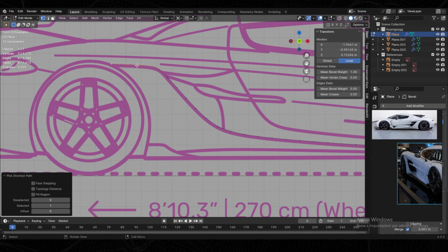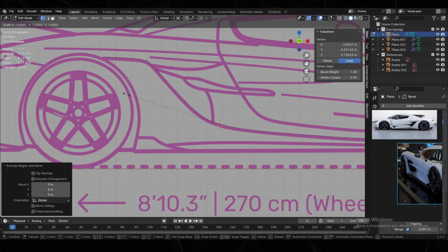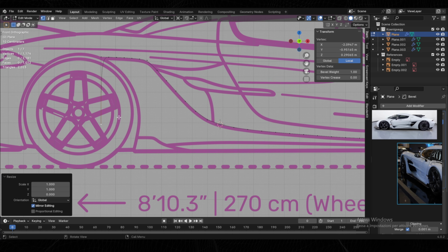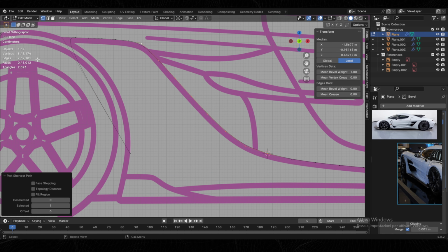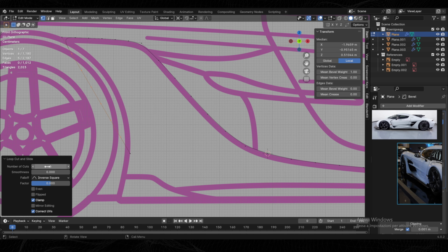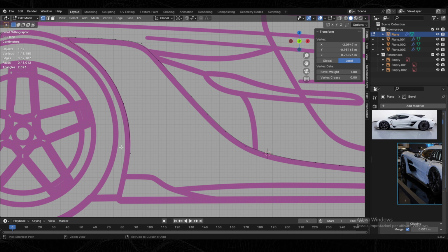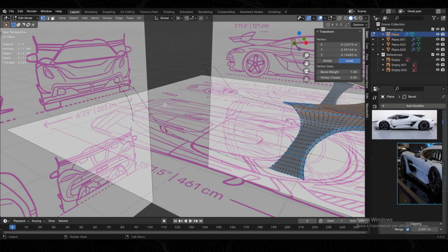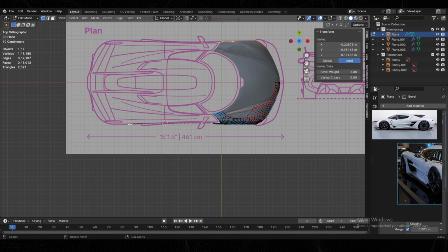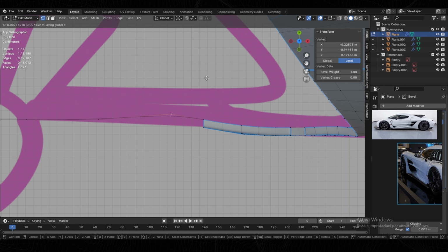And to complete outlining this part here, place your 3D cursor on this vertex, extrude this other vertex, and bring it to the same height as your cursor with S plus Z plus 0. Then add 6 loop cuts and adjust them on the blueprint. Now, before giving thickness to this part of the car, adjust the vertices we have just created on the Y-axis too.